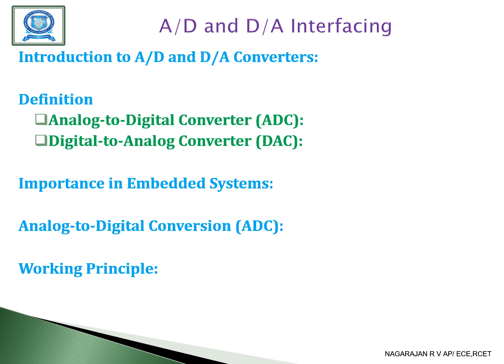Now let us see, one by one, the analog to digital conversion. What are the basic principles behind this analog to digital converter? The working principle, first one is sampling. Sampling is where a continuous analog signal is sampled at regular intervals to create discrete time data points. The rate at which this sampling occurs is known as the sampling rate. Next one is quantization. Each sampled value is then approximated to the nearest value in the set of discrete levels defined by the resolution of the ADC.